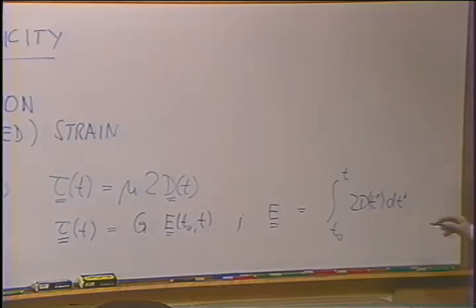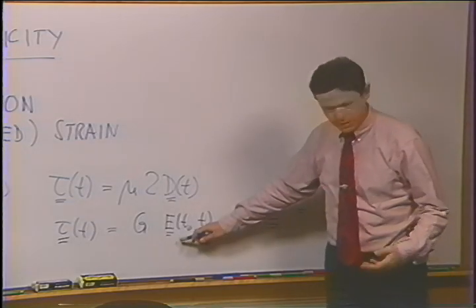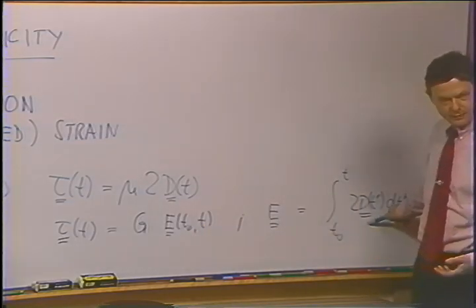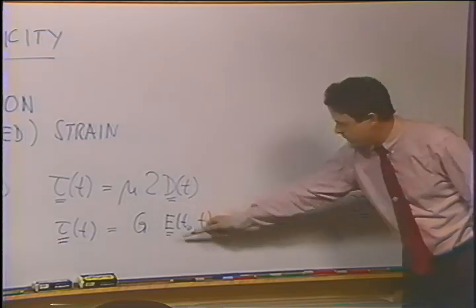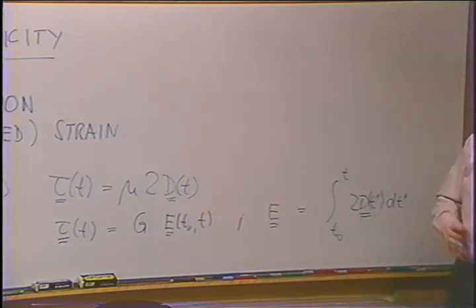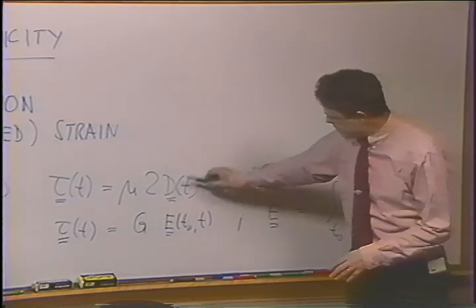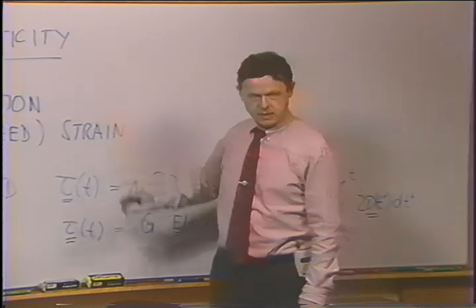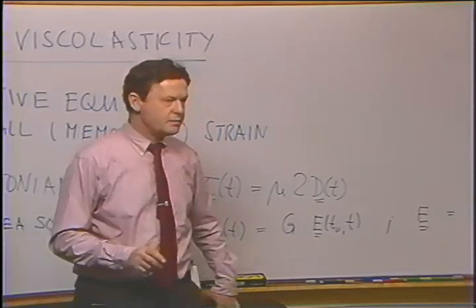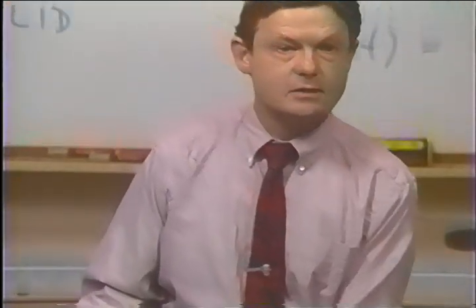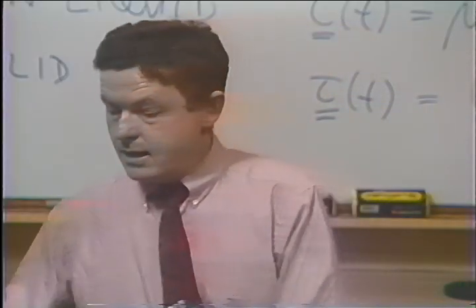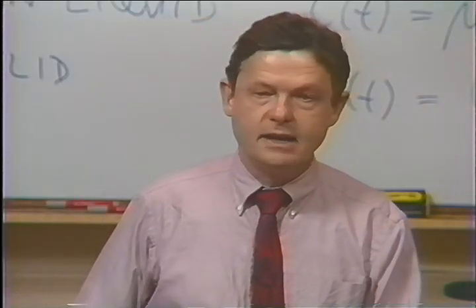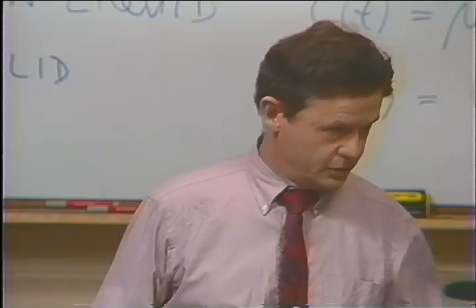So something like this. I had to introduce a small strain measure here when looking at the rate of deformation tensor. Later on, we will, of course, replace this with the Finger tensor or Cauchy tensor and then go to large deformations. But these will be limiting cases for our constitutive equations, which we have to derive. Now, I will derive this equation, which we will call the Boltzmann equation. It's based on Boltzmann's linear superposition principle. I will derive that with a phenomenological approach.